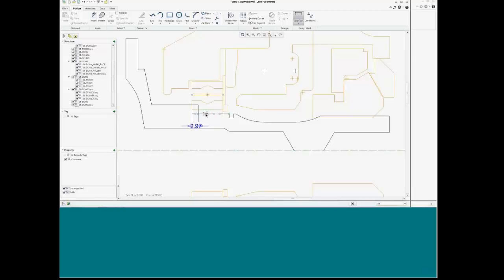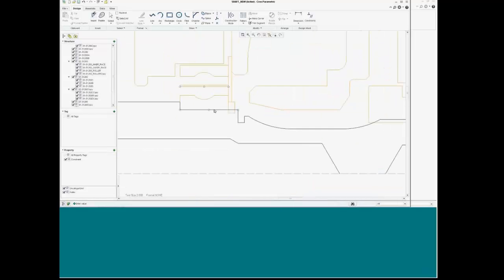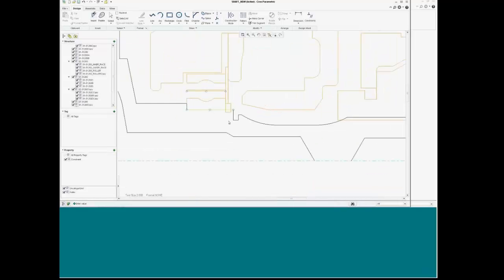to very easily get our geometry to where we need it to be. So this dimensioning is simply a tool, can zero these out and get our lines where they need to be, and since they were just used as a tool, we don't need to keep them, we can just delete them. So now we have our bearing retainer in this place where it needs to be.